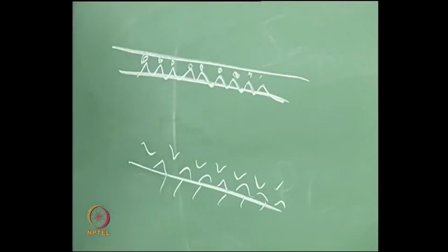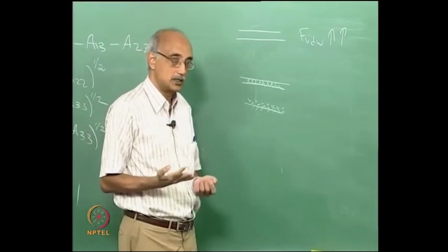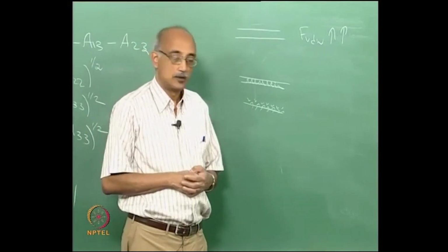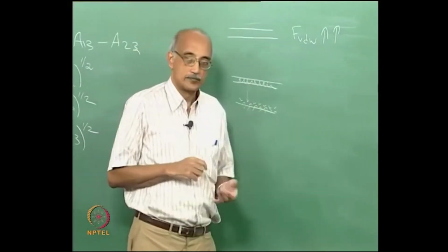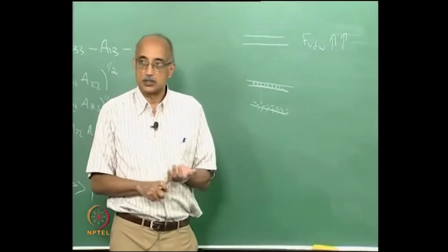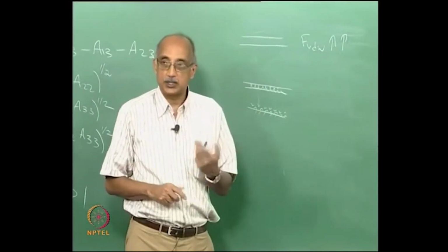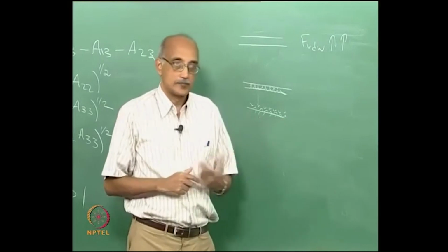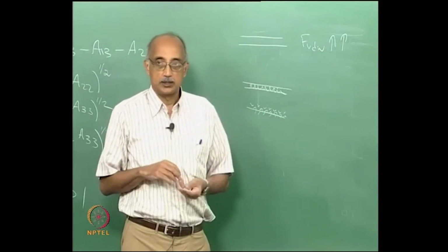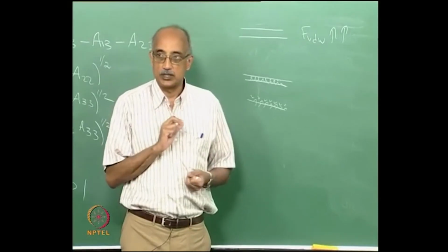Well, that depends. Sometimes it leads to reduced forces, but sometimes it can lead to this interlocking mechanism that we talked about, and it can actually result in an increase in the adhesion force. But clearly the point is the physical properties of the particles and the surfaces, including their hardness, deformability as well as roughness, also play influential roles in determining the forces of adhesion between these particles.